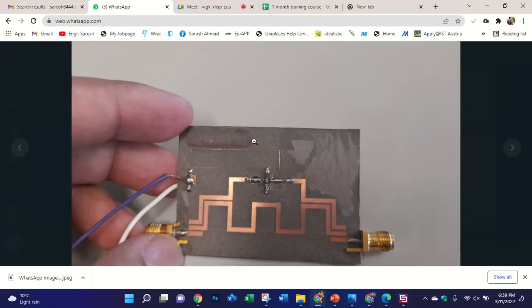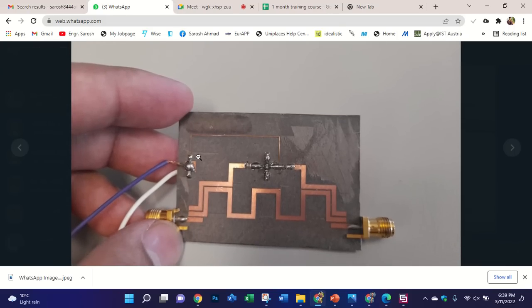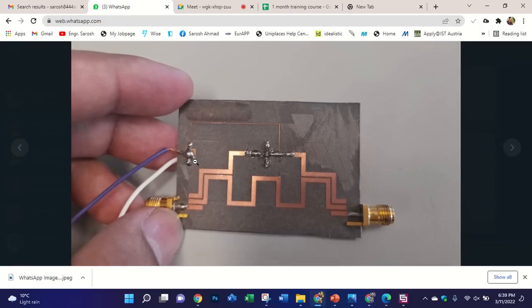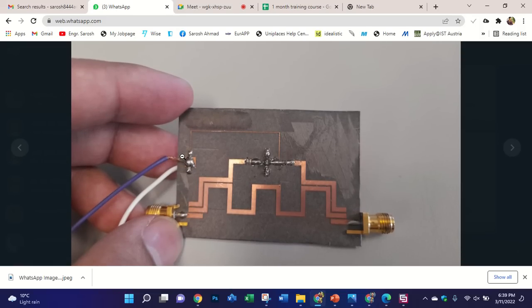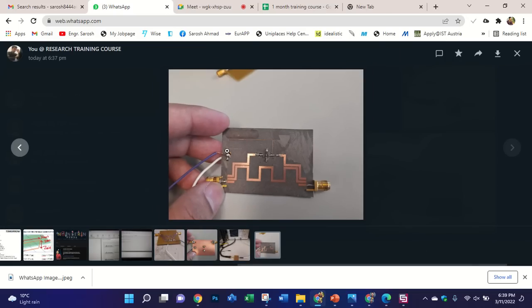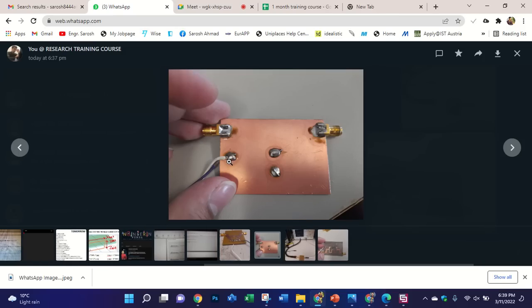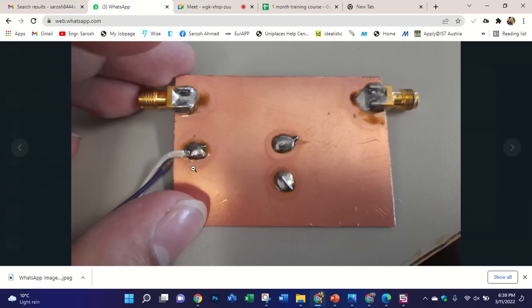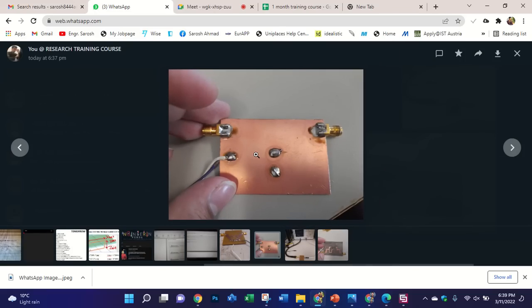They created another strip line, a very small thin line, to connect with the diode, I mean with the capacitor and resistor here. Then they provided the voltage at this point. Then they used a shorting pin that is connected with the ground plane. On the other side they used the ground plane and soldered the wire of the ground plane to connect with the DC supply. So in this case you need to use a shorting pin to connect with the ground.